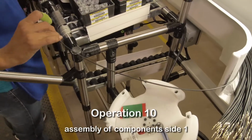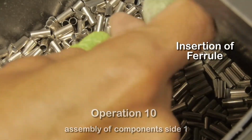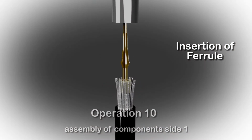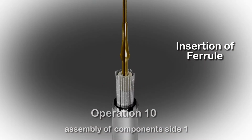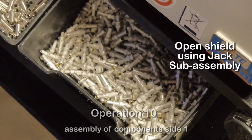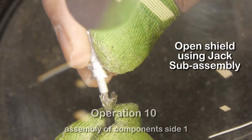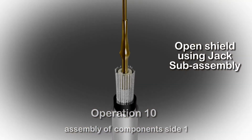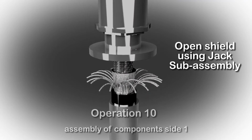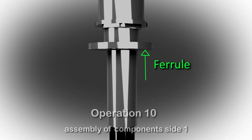Operation 10 includes assembly of components on one end of the cable. It includes inserting the ferrule over the cable. Open shield using the jack subassembly and insert it over the pin contact jack. Slide the ferrule until it makes contact with the bottom flange of the jack subassembly.